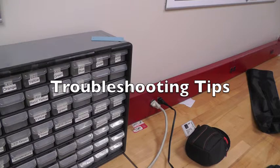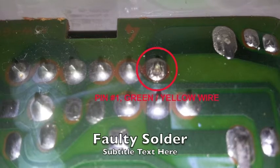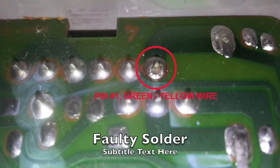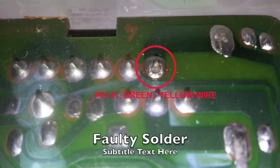If you are running into difficulty with data acquisition initially, your problem is likely with the hardware. You should first verify that all wires connecting the accelerometer to the Arduino are going in the proper Arduino ports. If they are, you should also verify that the wires are properly soldered to the accelerometer and that all connections are good.